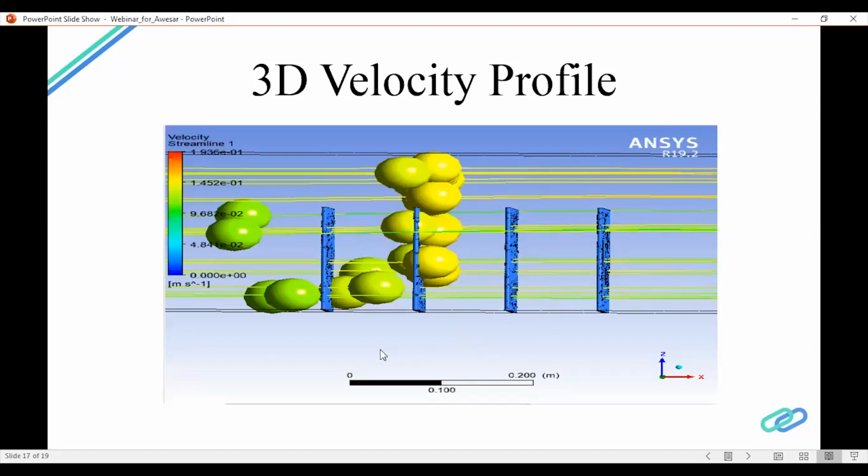Now, if you look at a side view of the velocity, so you stand in here, and this is your river. We have lots of small trees and grasses or vegetation inside the river. We draw the velocity profile by this picture. So we use the circle ball to demonstrate the velocity profile. That's the speed. When the flow comes in, it will hit the vegetation, and because of the drag, it will look like this. It will bend, looks like this. So it will slow down.